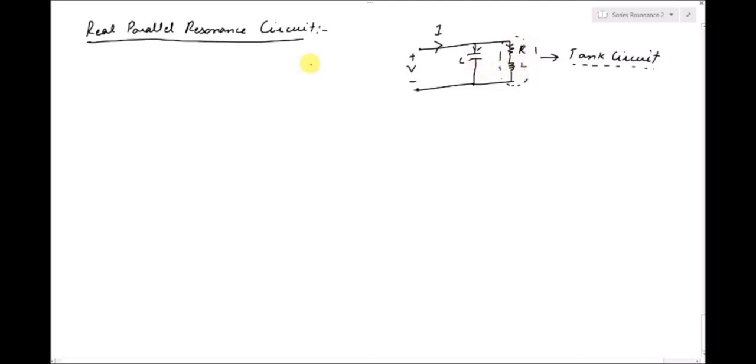So now if I have to find the admittance value, that will be Y is equal to j omega C plus 1 over R plus j omega L. So that was the inductive susceptance. So we have added the resistance value with the inductive reactance value. So when I will take the inverse, that will become the admittance. So after solving, it will become j omega C plus 1 over R plus j omega L into R minus j omega L over R minus j omega L.